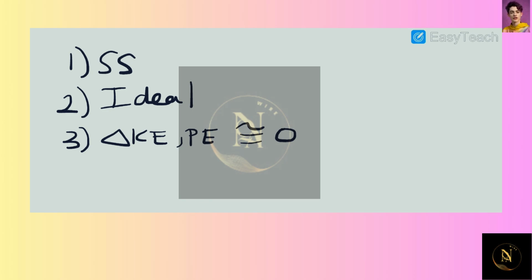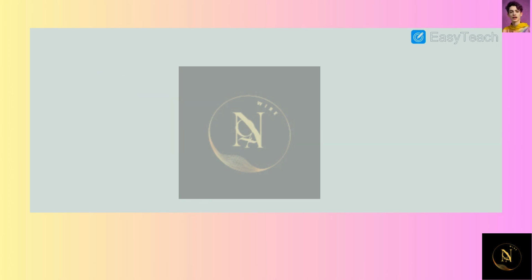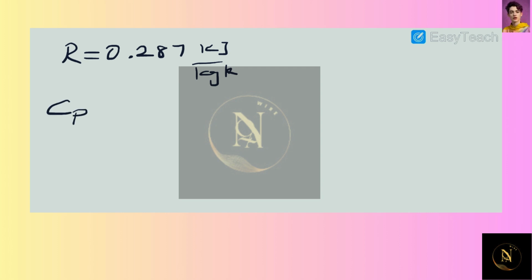Now what we're going to do is go ahead and write down the properties of our air. Since we are dealing with air and it's an ideal gas, we can say that R is equal to 0.287 kilojoules per kilogram Kelvin. The specific heats of air, Cp, is equal to 1.005 kilojoules per kilogram Kelvin, and our Cv is equal to 0.718 kilojoules per kilogram Kelvin.